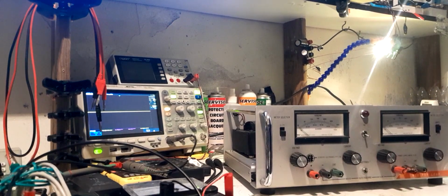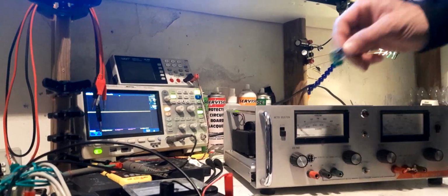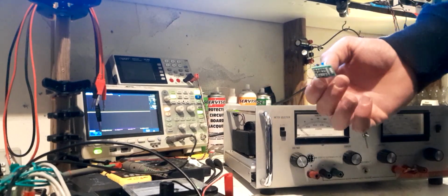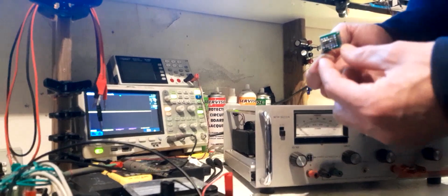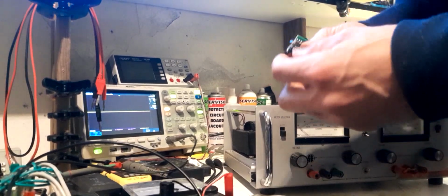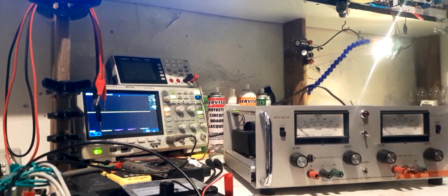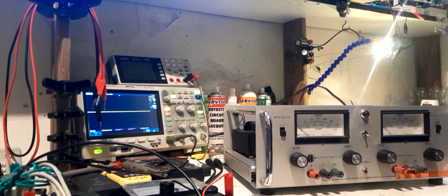Last time, the electrolytic cap I mounted as close to it like you should, but the MKT was an afterthought, so it got tacked on the other side of the board, all the way at the other end of these leads. I'll just do it all on the one thing and try to keep both caps as close to it. Alright, I'll go do that.